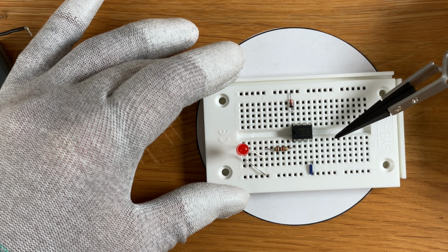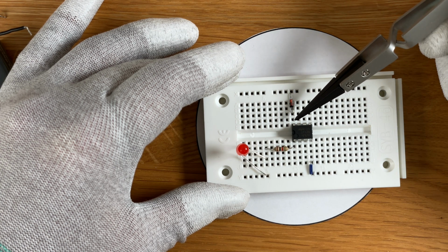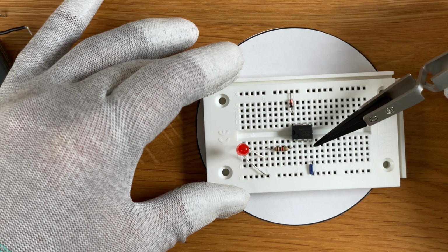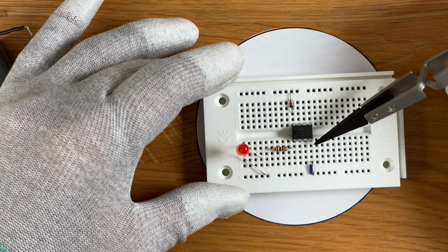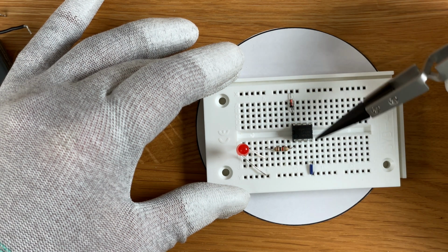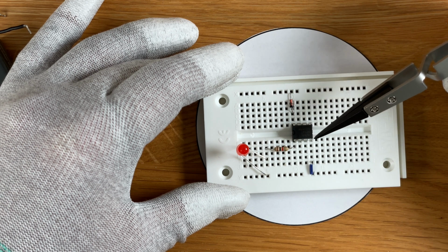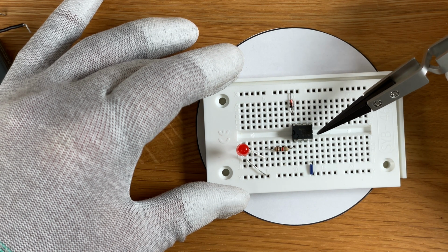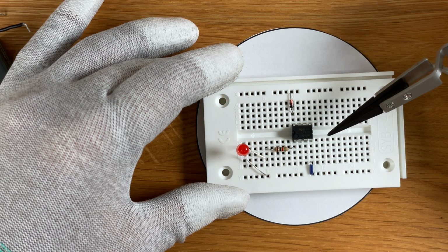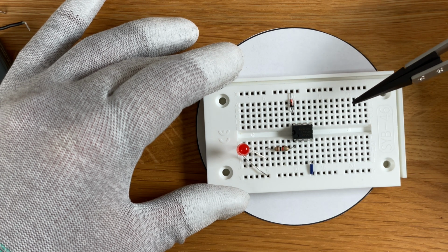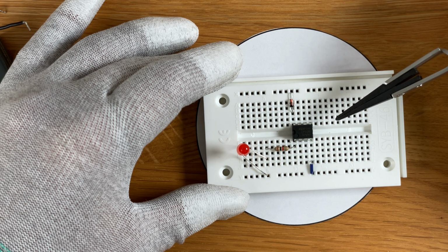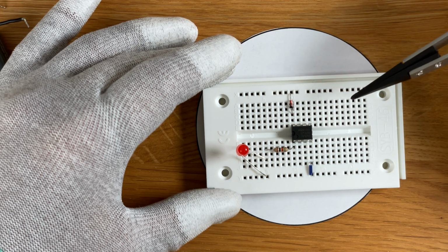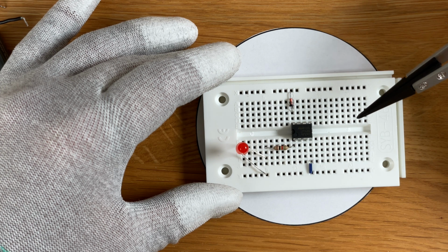If you look it up on the data sheet, you will find that this pin here is for positive power, and this one is for negative power connection to the battery, and the other ones on the upper side and on the lower side lead to two separate operational amplifiers. That means inside this housing there are actually two op-amps which we can use. In this circuit, however, we are only using a single one, and this single one is connected to the lower side.